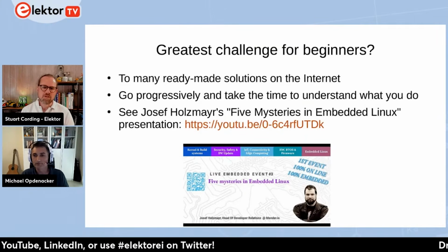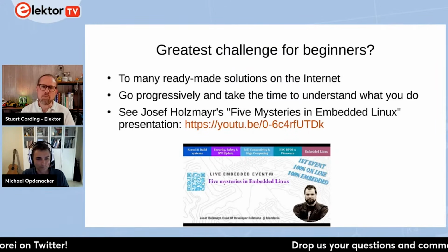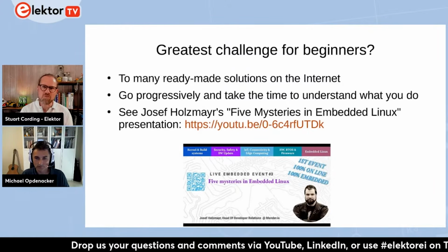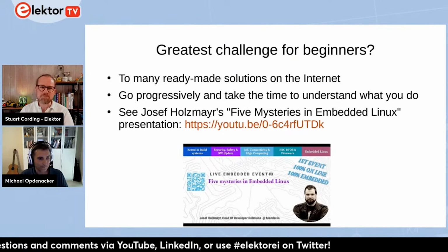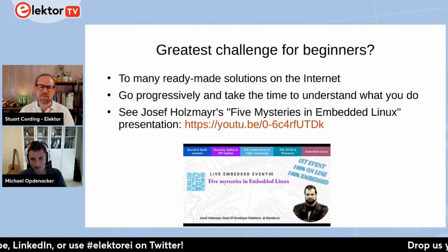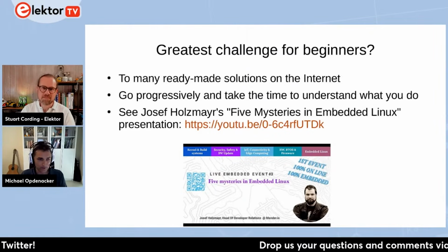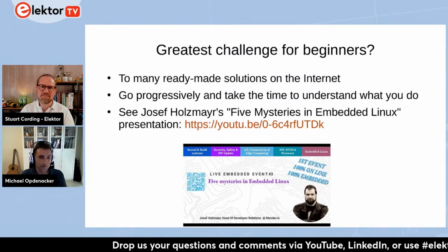And for those examples that you gave in terms of getting started and bringing up a board, do I actually have to also run Linux on my development PC as well, or are there ways of doing it from a Windows PC? It's recommended to use Linux as an environment for building all this, because otherwise it's complicated. You'll be the only one doing that. So at least use a virtual machine. Yeah. With Linux on it.